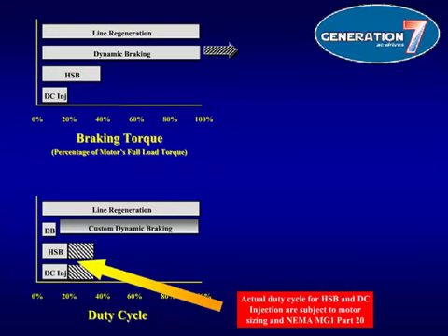High slip braking and DC injection duty cycles vary depending on the parameter settings and the motor sizing. The duty cycle is subject to meeting the NEMA MG1 Part 20 standards.